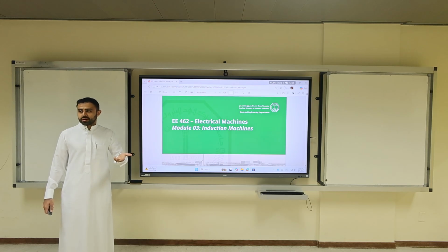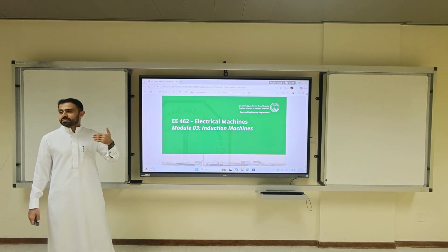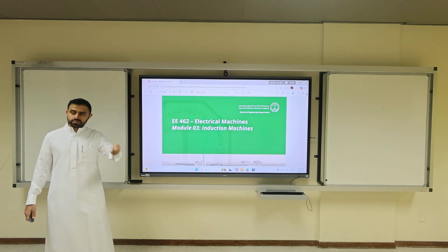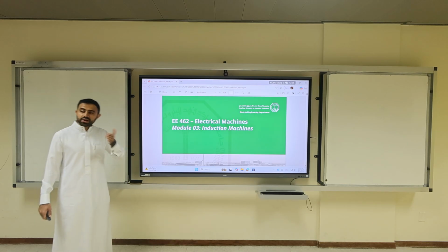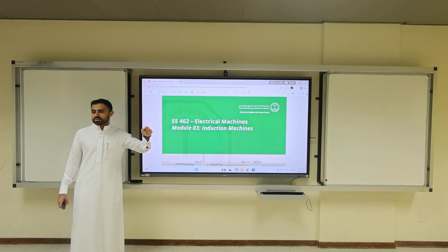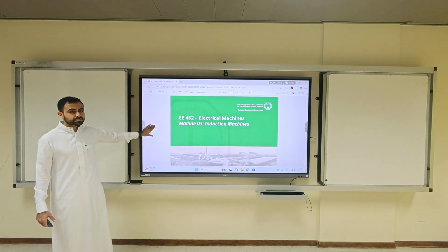It will burn. A few years ago, you remember we used to burn devices because we plugged a 110 device into a 220 plug. So you cannot exceed rated voltage because you have so much current. V over F, after rated voltage, we enter into, what's the name of that region? Flux weakening. So this is most likely a target question in the test.